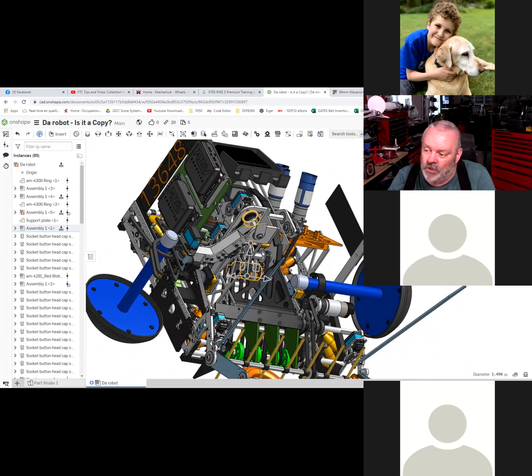Wow. And that requires him to use a control hub and an expansion hub. And you're allowed to do that. These communicate with an RS-485 connection, so they have a private little network that they run on. You really only talk to and program one of them, and the other one is used as a slave. Does that make sense? Yeah. You can have up to 2 of these modules on your robot: one control hub and one expansion hub.